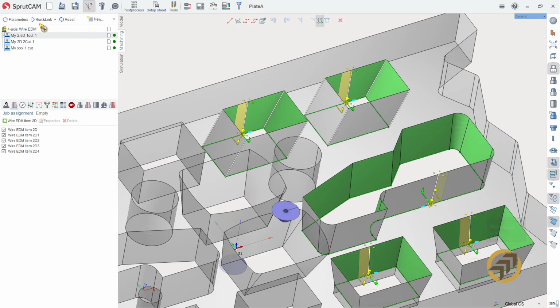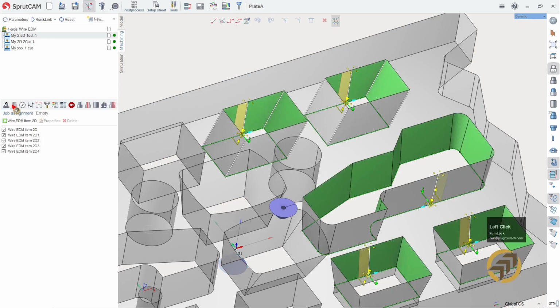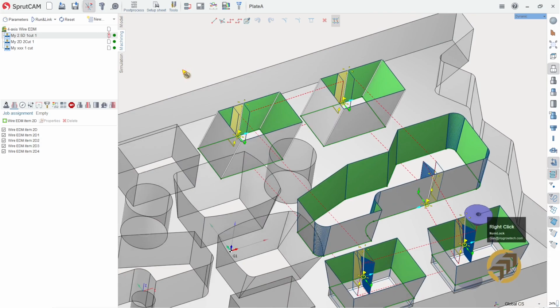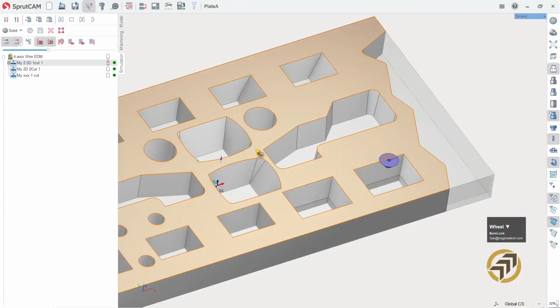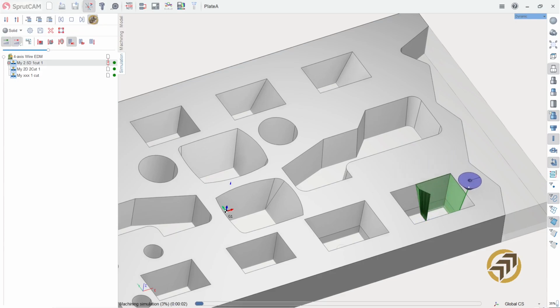Before you click calculate, let's double check. Make sure the two connectors always use lower guide. Always use lower guide, and then you just run, and that's it. And we can go for simulations. This is the 2.5D pocketing.